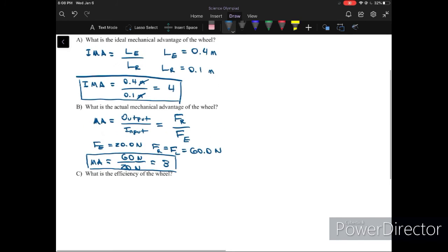Well, for some reason, the ideal mechanical advantage of 4 wasn't achieved. Jill had to apply more force than the 15 newtons it would take if the ideal mechanical advantage was accurate for the system. So there were losses somewhere along the way. And my prediction is it was likely due to friction. Most wells weren't built thinking of perfect lubrication and a frictionless system.